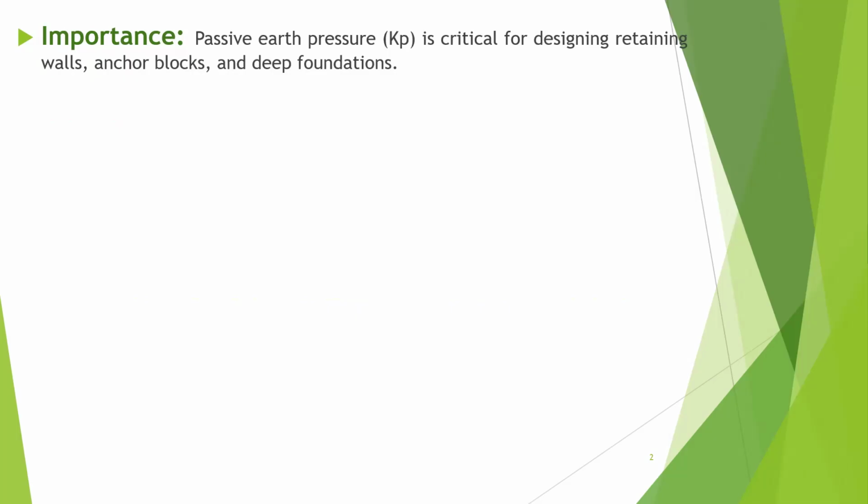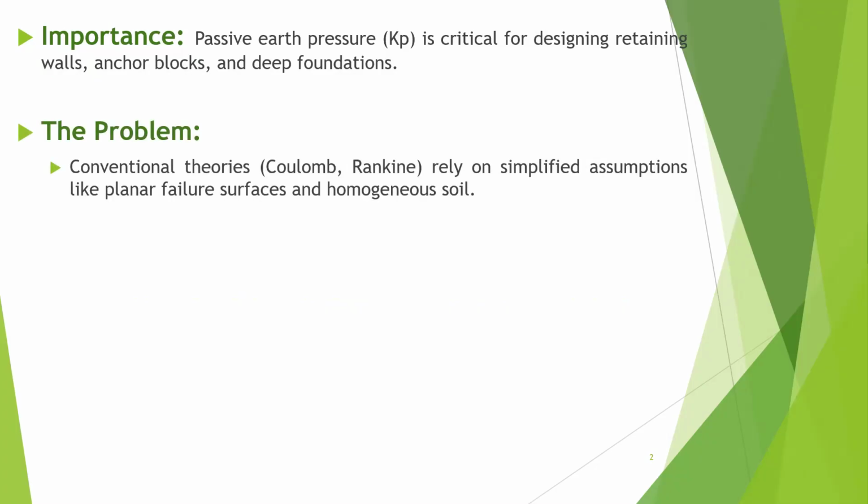Importance of our study is that the passive earth pressure KP is critical for designing retaining walls, anchor blocks, and deep foundations. The problem: conventional theories, Coulomb and Rankine, rely on simplified assumptions like planar failure surfaces and homogeneous soil.